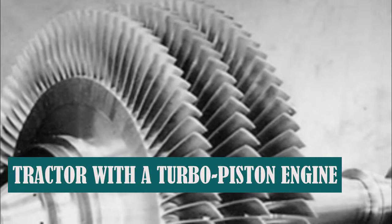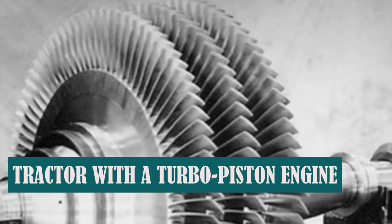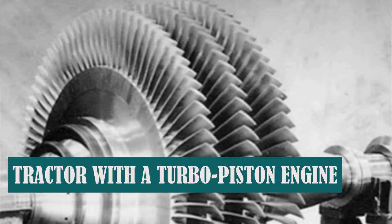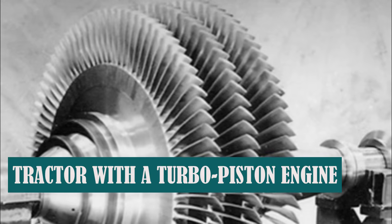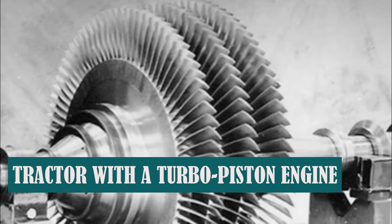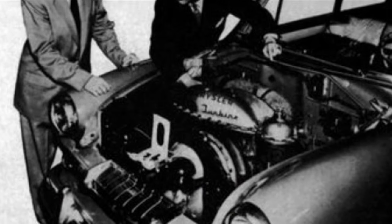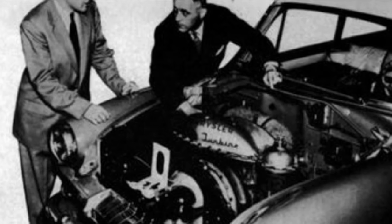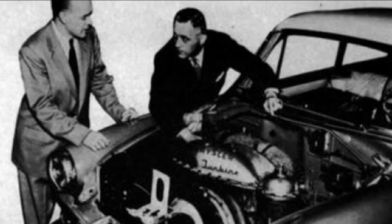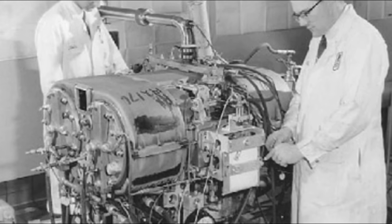Advances in global engineering in the development of highly efficient and economical gas turbines by the 1950s allowed machine builders to attempt to use various gas turbine engine designs in automobiles and tractors. The most suitable option for using a gas turbine as a propulsion engine in such vehicles at the time was seen as a hybrid piston turbine engine, which combined two separate units, a piston gas generator and a gas turbine